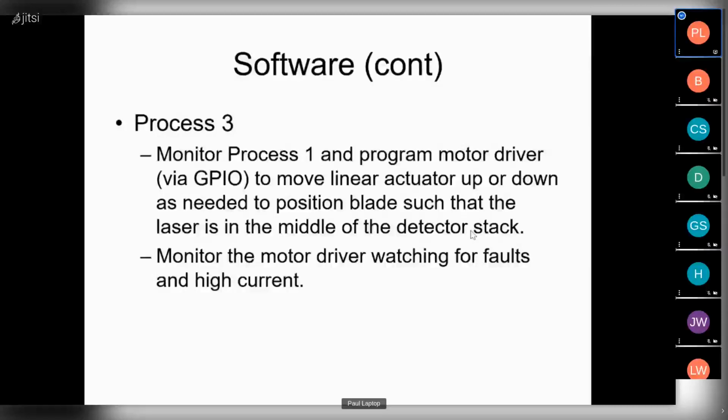My hope is that by running this frequently, the absolute difference across the arena will get smaller and smaller, and this will just be a maintenance thing, where I'm trying to grade out the last 1 inch across 100 feet as opposed to the 10 inches that are currently present.